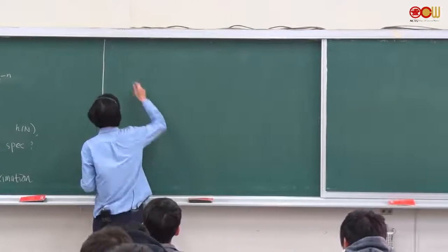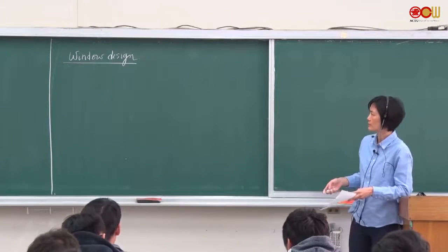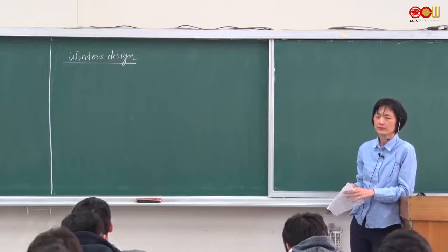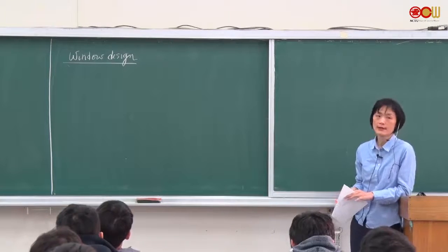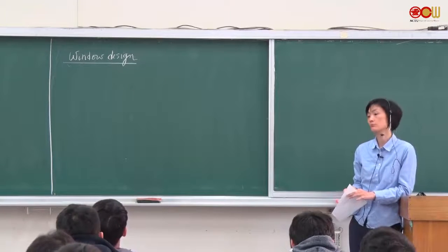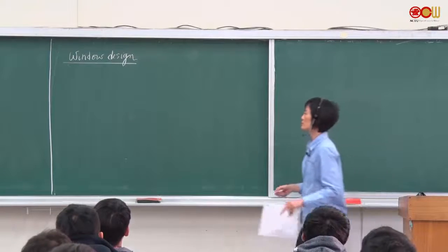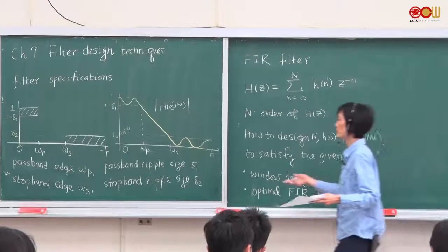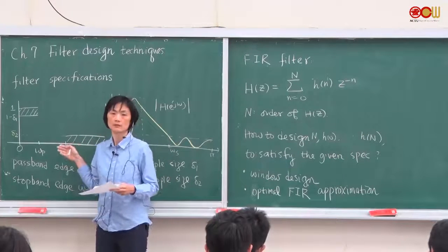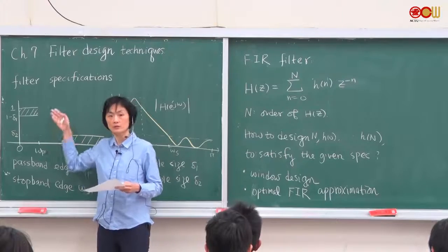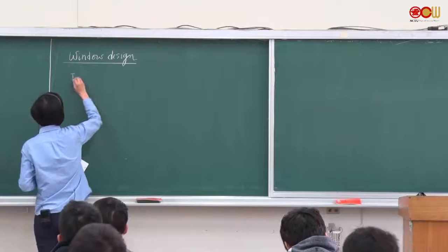So window design. When people start on designing an FIR filter, they don't really have a clue how to design it. But they do know that the ideal filter is the best, right? We know the ideal low-pass filter. With the ideal low-pass filter, you will be able to get the ideal response, right? So let's recall the ideal low-pass filter.